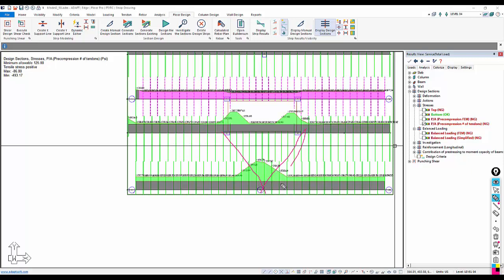And so we had 2 here on one side, 2 on the other, and where those intersect on these section cuts here, we get kind of double the force, and we get double the pre-compression because of how those converge down to that column. So those are little things you want to watch out for, and then we have fairly high pre-compression here again as well as there.